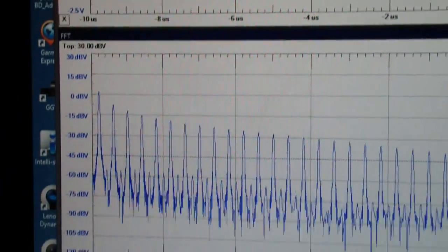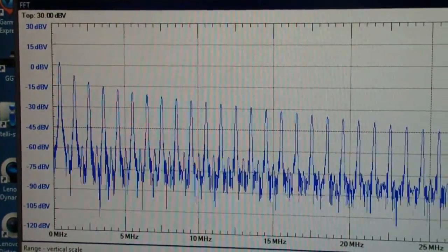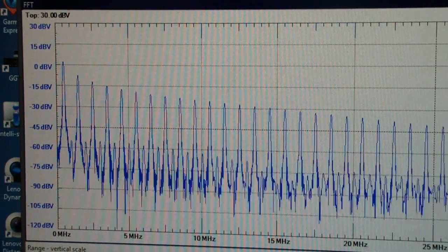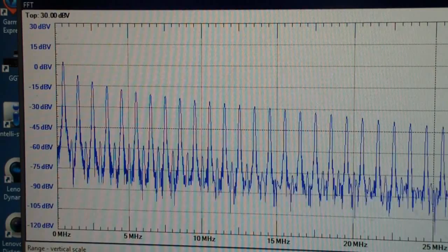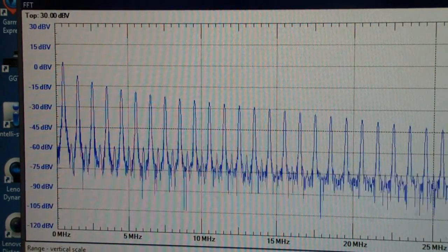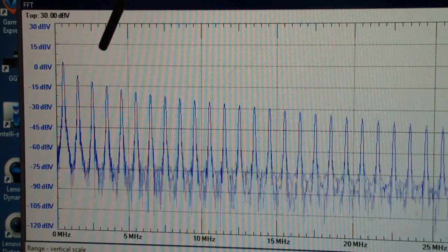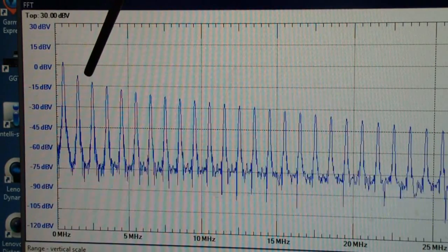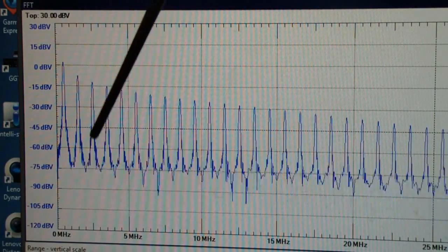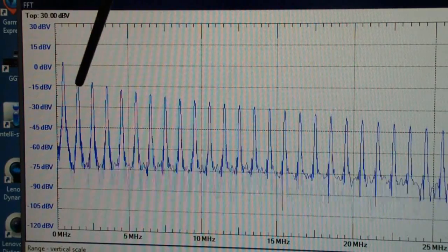And then down at the bottom is the spectrum. We'll talk a little more when we get to talking about spectrum analyzers themselves, about how this actually divides up. But fundamentally, when I was talking a little bit ago about resolution bandwidth, that is, for example, how narrow a frequency you can resolve in the FFT is called the resolution.